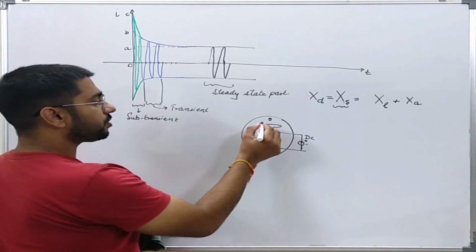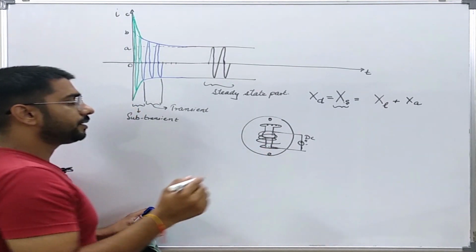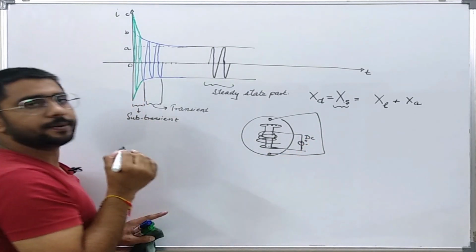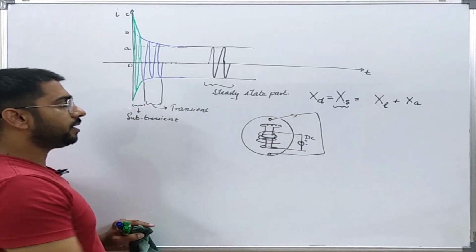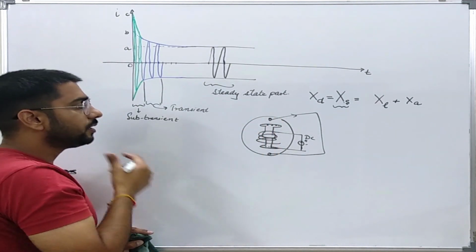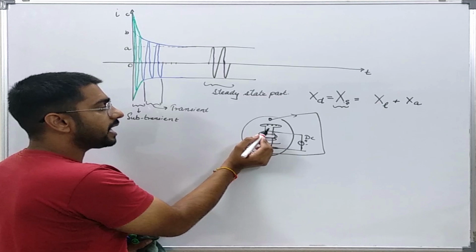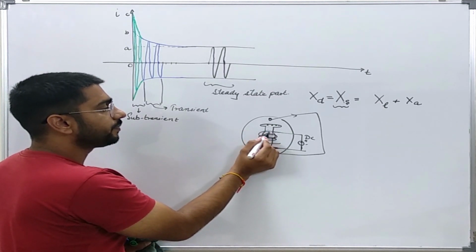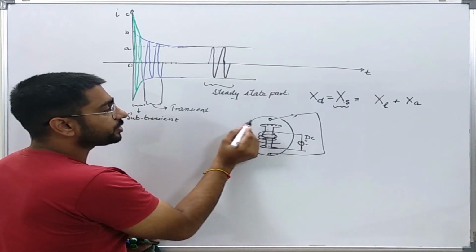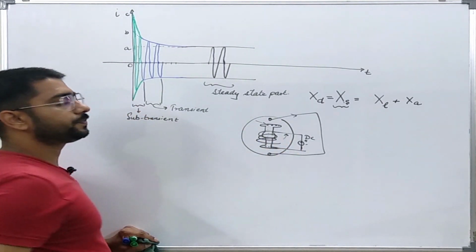Now this rotor is provided with damper bars or damper winding. When suddenly a current starts flowing through this coil, it will try to induce a flux which is going to oppose the existing flux. To avoid that, due to Lenz's law, there will be induced eddy currents in the iron, as well as induced currents in the damper bars and the field winding also.